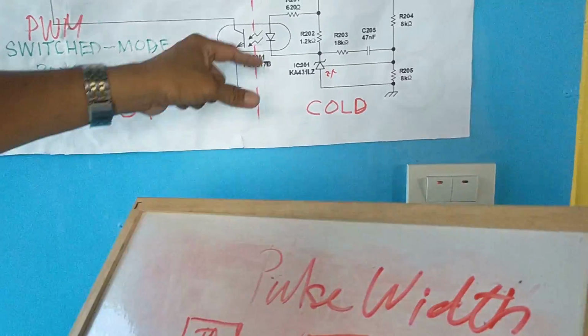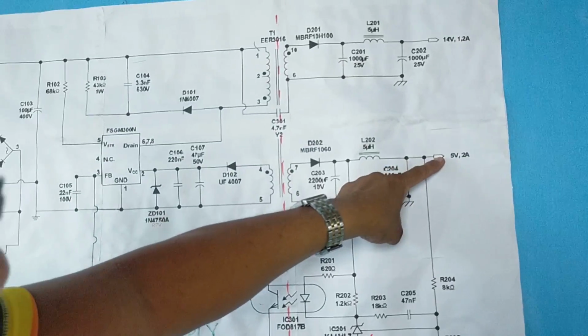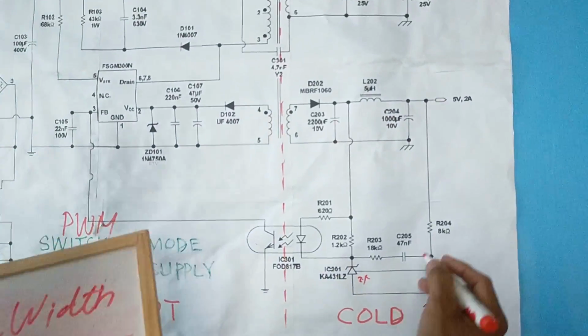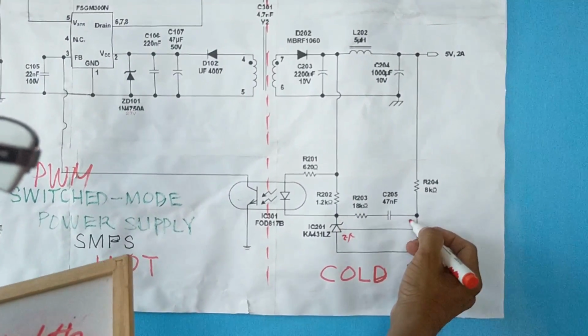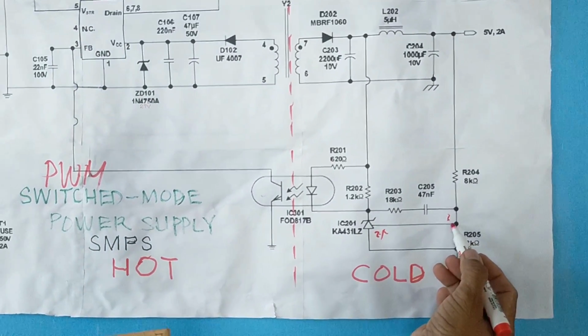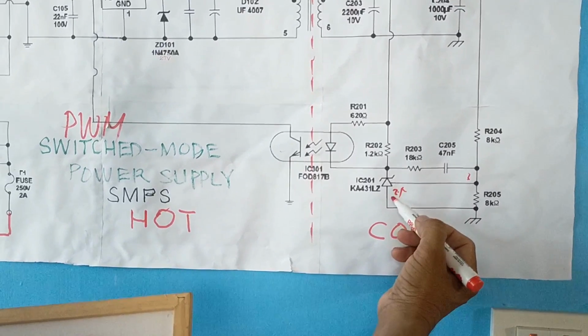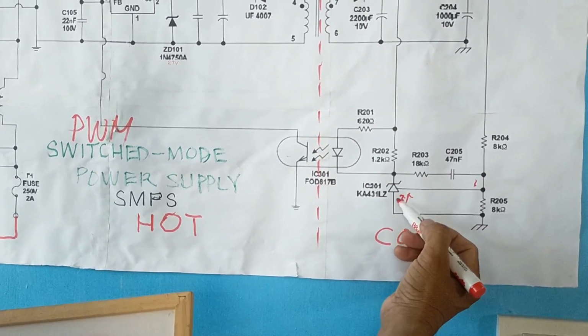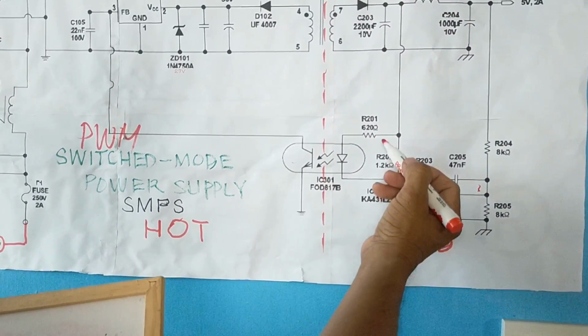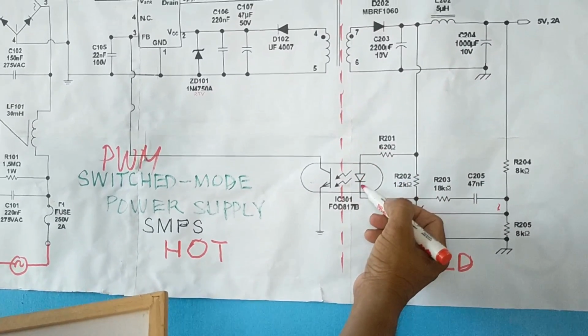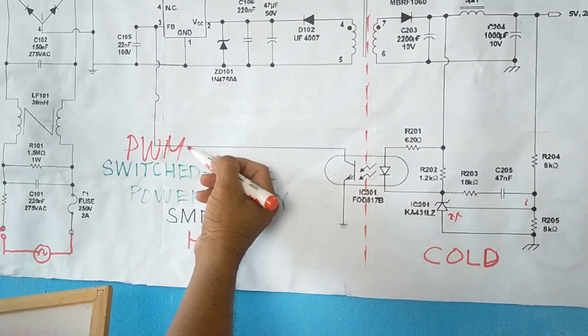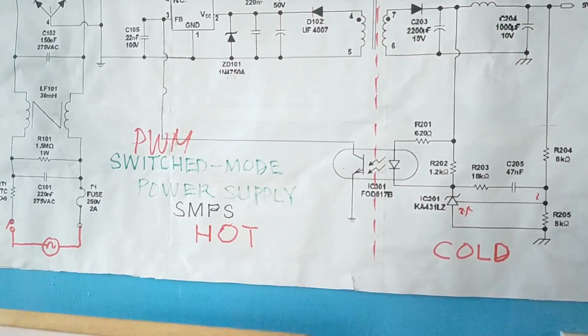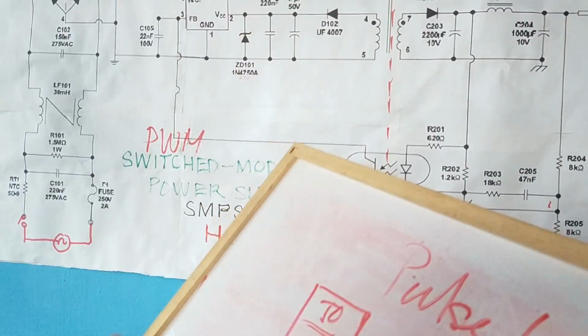But in case the voltage increases to 6 volts from 5 volts, so 3 volts here is actually higher than the reference voltage of 2.5. So there's an increase. So that will be submitted to the controller here. So there's a need of reducing the operation of the transistor here.